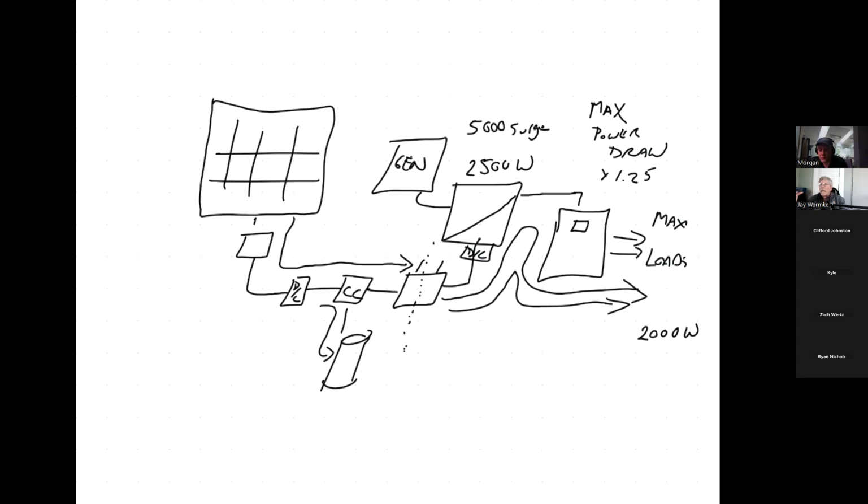That's because that load for that second drew a huge amount of power, which then caused the voltage within your home to fall a little bit until that surge evened itself out. So your refrigerator, when it first kicks on, maybe it draws 1,200 watts. And then after a second, it's only drawing 350. So you've got to account for that surge.